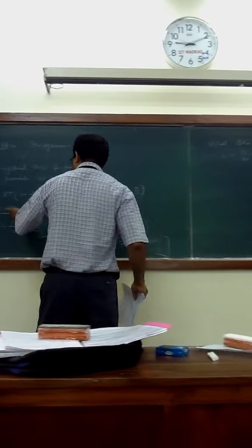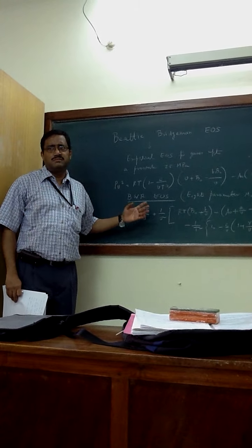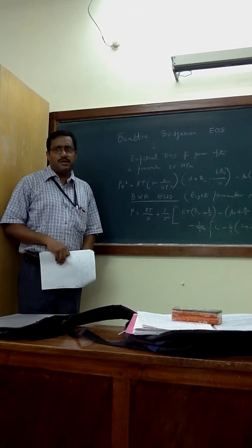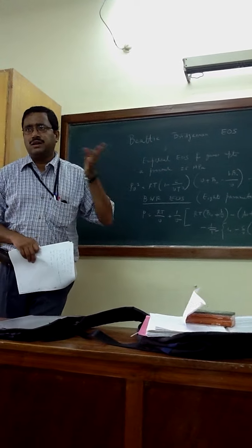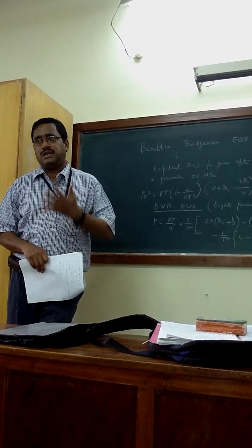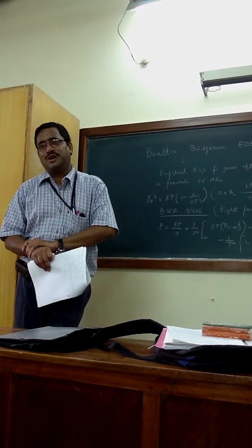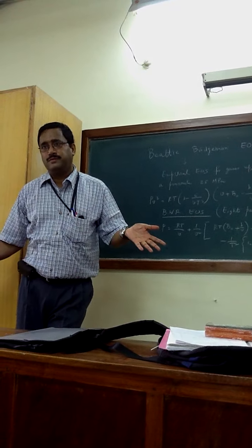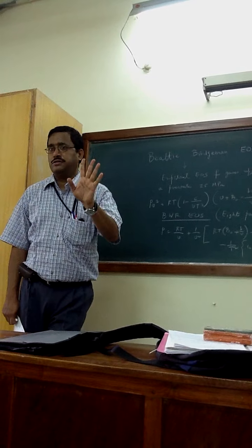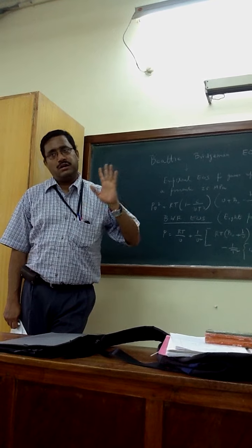So based on this Benedict-Webb-Rubin equation of state, it is possible to have Z, because you know that if you have the compressibility factor then you can write in terms of reduced state. Then also for the second class equation of state, we can have a material invariant form. Material invariant form is so beautiful. It will be applicable to any material. Your one graph is sufficient. Any material you can apply. Excellent idea. So the same thing you can apply for the other equation of state.